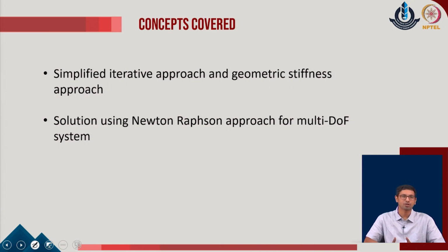Now, if we add the contributions of the geometrical stiffness, and we are also able to identify the procedure to add the P delta contributions, we will be able to comprehensively transfer the same codes to the regular nonlinear analysis procedures. Okay.